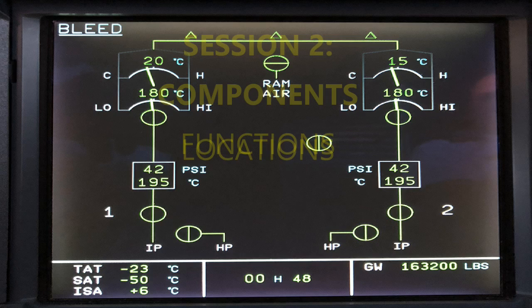Okay, you also have that thermostat. It is called the fan air valve control thermostat, but it can also be called the temperature control thermostat. So if you see TCT, that's for temperature controlled thermostat. That's the fan air valve controlled thermostat, and of course that's downstream. It's going to control the engine fan cooling airflow in order to maintain, remember what I said before, that 392 degrees Fahrenheit.